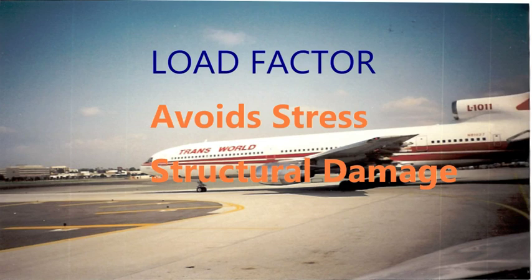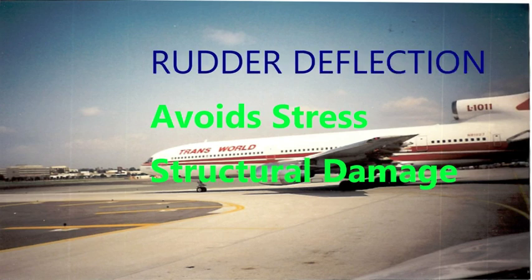The next thing is your rudder deflection. You can have it at max range, but if it does exceed a certain deflection, then you're going to have a different situation, what's called a rudder hardover, and that definitely is going to affect the structure of the plane, and it's going to be disastrous. So that's what you have with the rudder deflection.